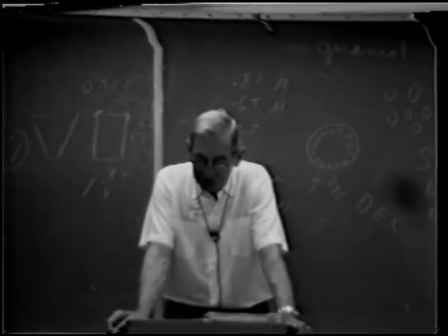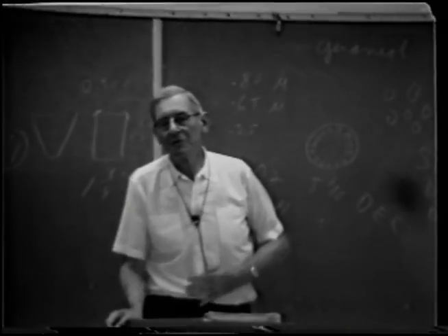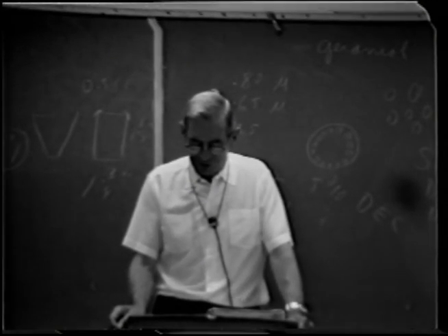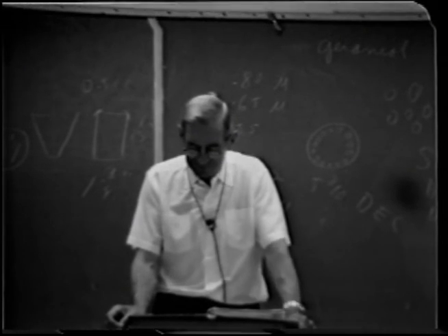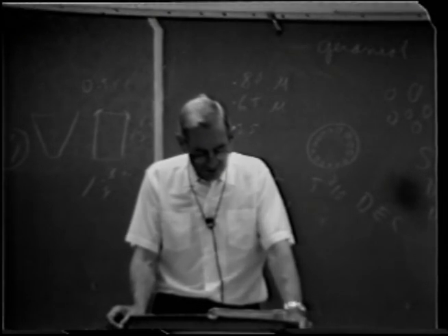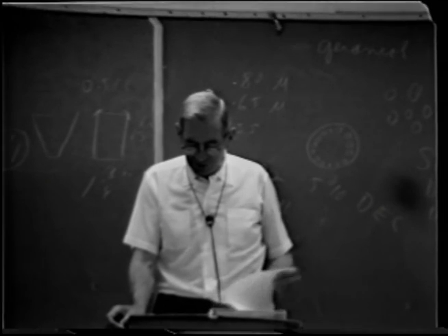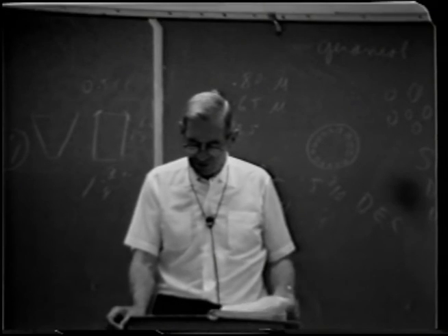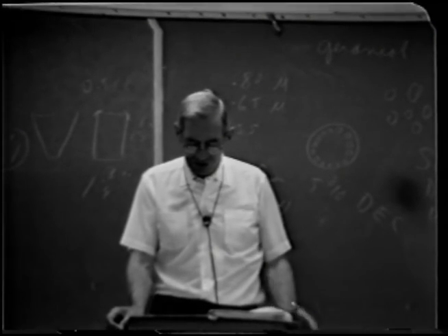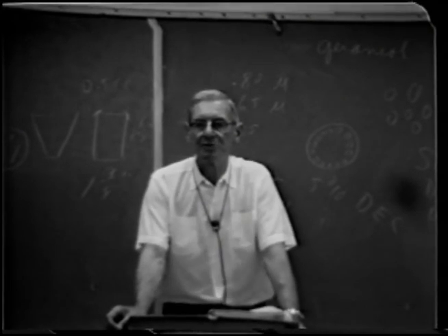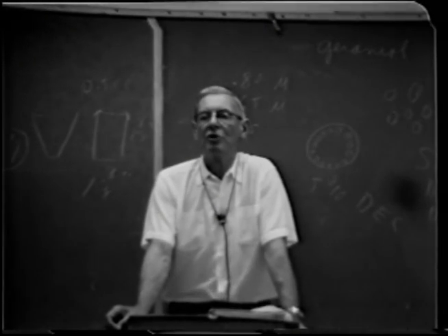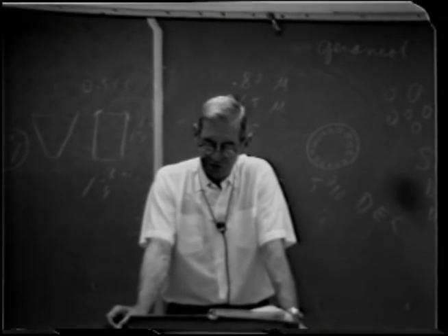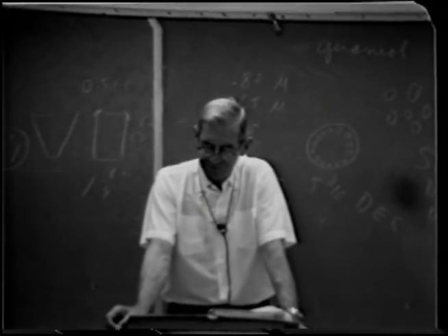Before bottling, it's necessary to determine if the wine is stable. That's self-evident, but sometimes it is forgotten or overlooked or not given the importance it should have. You should determine the amounts of copper and iron, test for heat and cold stability, and in addition, it's highly desirable that the wine be tested for the presence of protective colloids by the method I gave you in the previous lecture.